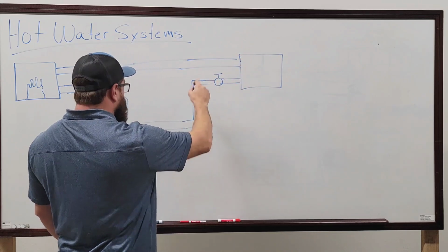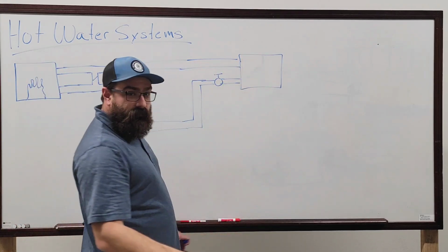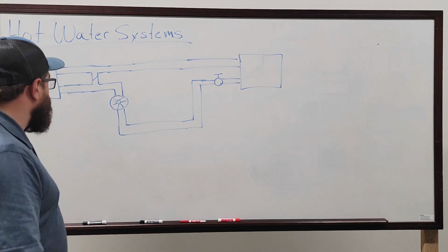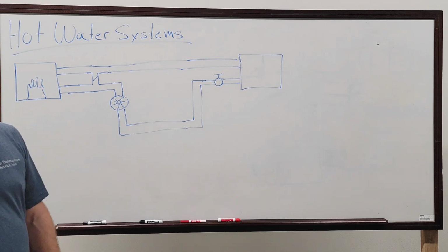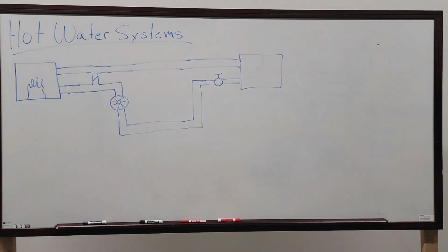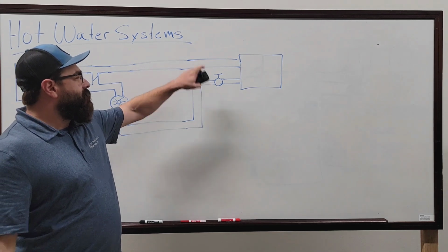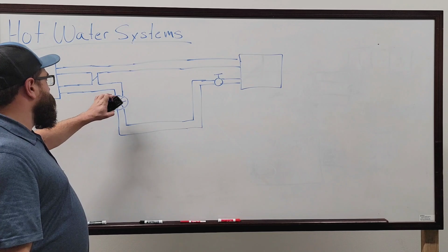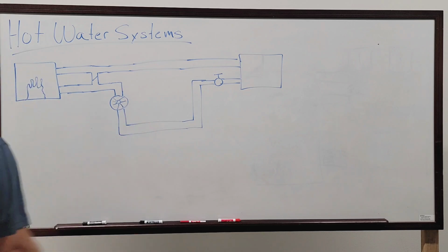Yeah, I know that, so then it would come into the pump and then into the boiler and then out, hot water into it, right? I'm just trying to teach this correctly. I don't want to tell people incorrectly. I know that there are systems where the pump is on the other side, but it's supposed to be on that side. I know the valve is on the return, that's a given, but I didn't know if... all right, so it has to be there because you're not pumping through hot water. Duh.